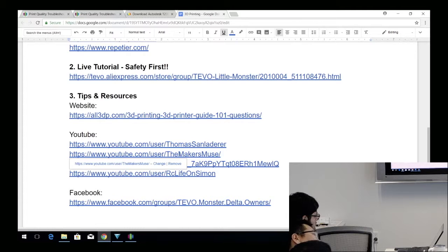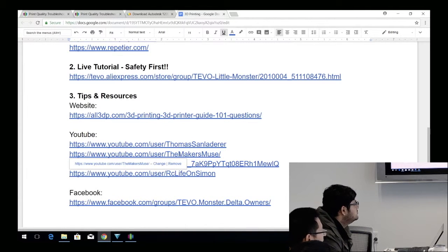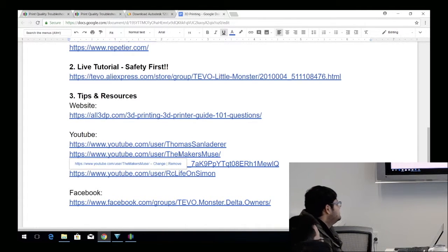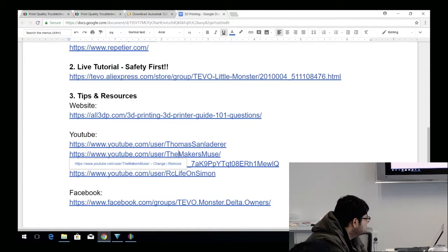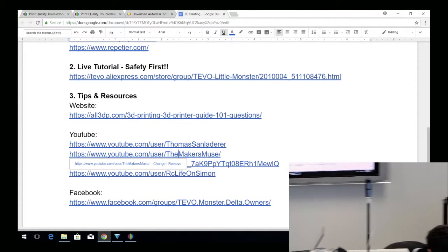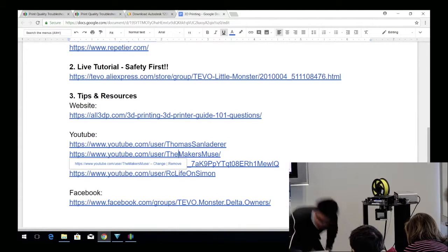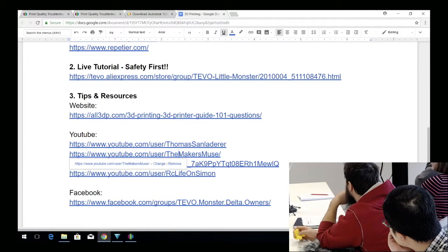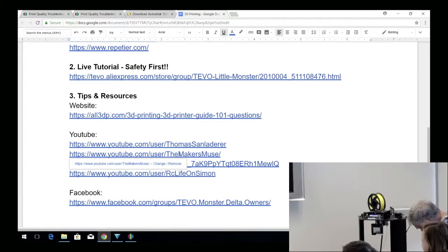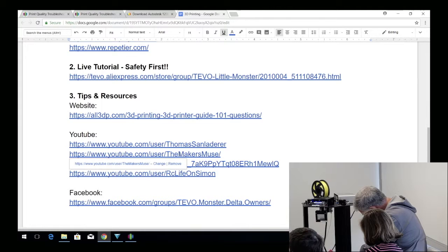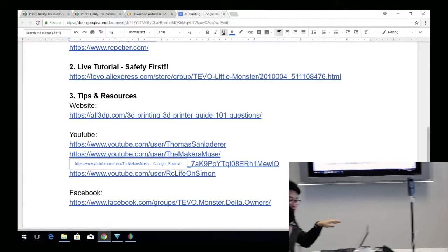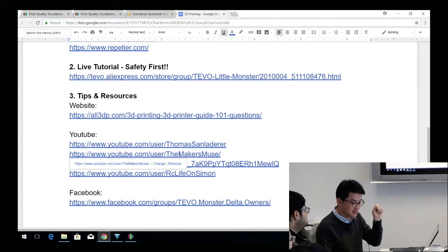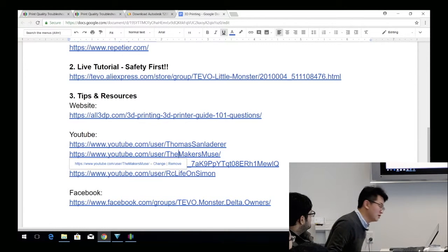So you see, the skirt is pretty messy, but it doesn't matter. That's not what we want. The inner piece is really smooth. That's enough. Some extra I should remove, but that's okay. And don't use your hand like I did. Just use this tool to peel it off easily. Because the heat bed is really warm, it's really easy to peel. You won't destroy your model.